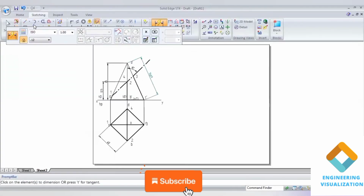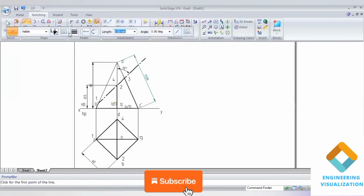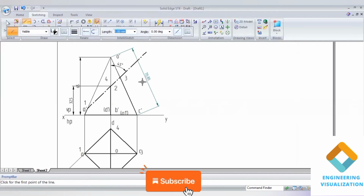Now using this slant edge length we will construct the development of it. For the same length we'll be drawing a line. Now we need to transfer all these cut points on the slant edge length. Okay, 1 and 4, this is an important step, guys.